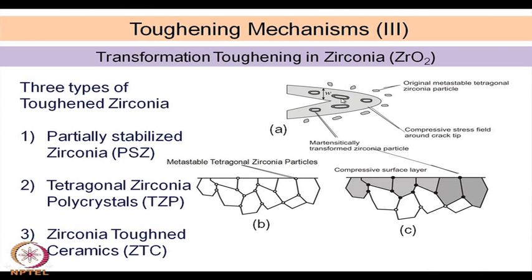In fact, that volume change is responsible for why a lot of cracks develop if you try to heat or cool pure zirconia through this temperature range. But stabilized zirconia does not have that, because it is more stabilized. There is no monoclinic tetragonal phase transformation. The cubic phase is stable throughout the temperature range, and therefore, that kind of crack generation is restricted or can be avoided.